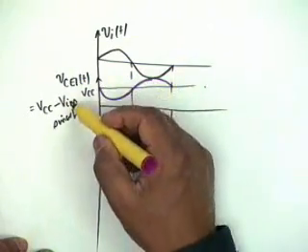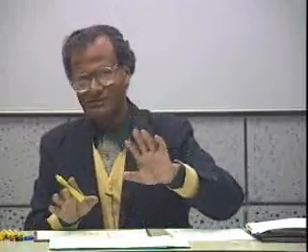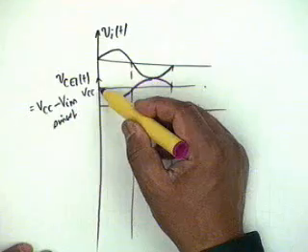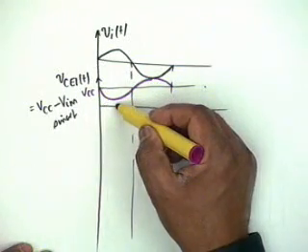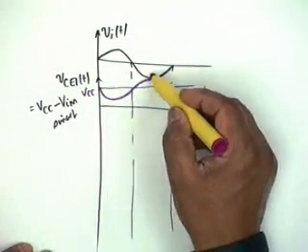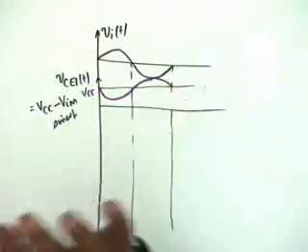We are showing that VIM, we are not assuming that VIM is equal to VCC. That means we are assuming that because it is a class A amplifier, it is not driven to the maximum. We will see what happens when it is driven to the maximum. So, the minimum that it can come to is 0, and the maximum it can go to is twice VCC, agree? That is the absolute maximum possible for VCE1T.